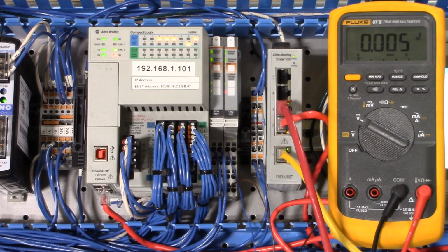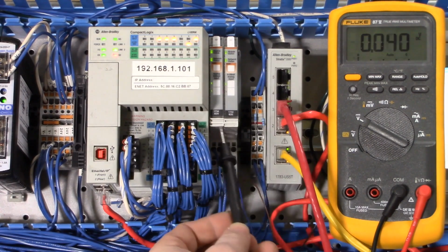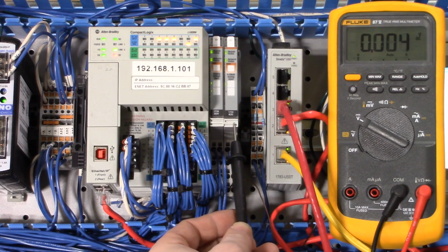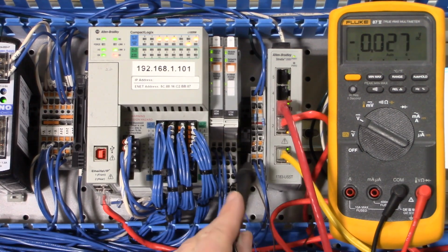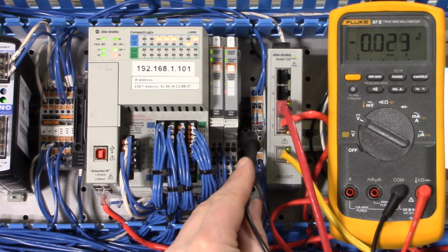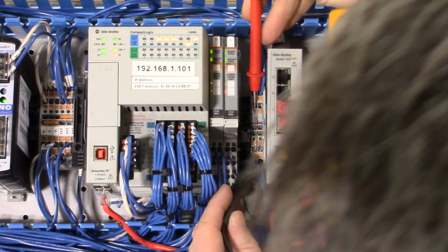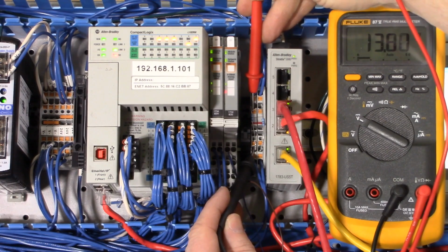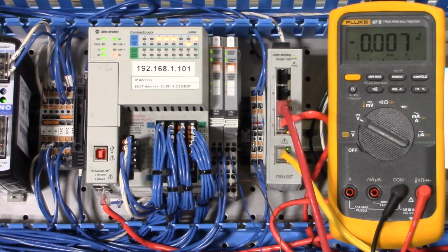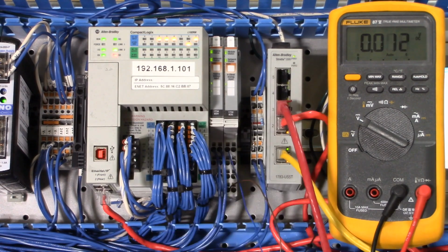So we have our camera zoomed in on our analog input modules. The voltage one is in this slot, and then there's the current 4 to 20 milliamp one. We'll talk about that later. The resistors we were just talking about are built into these terminal blocks. This is the 14 kiloohm resistor that's installed here. I've got the meter set up for DC voltage measurement, and we should be dropping about 14 volts. It's showing 13.8 across each of these resistors. The other 10 volts should be going to the input of analog channel 0.